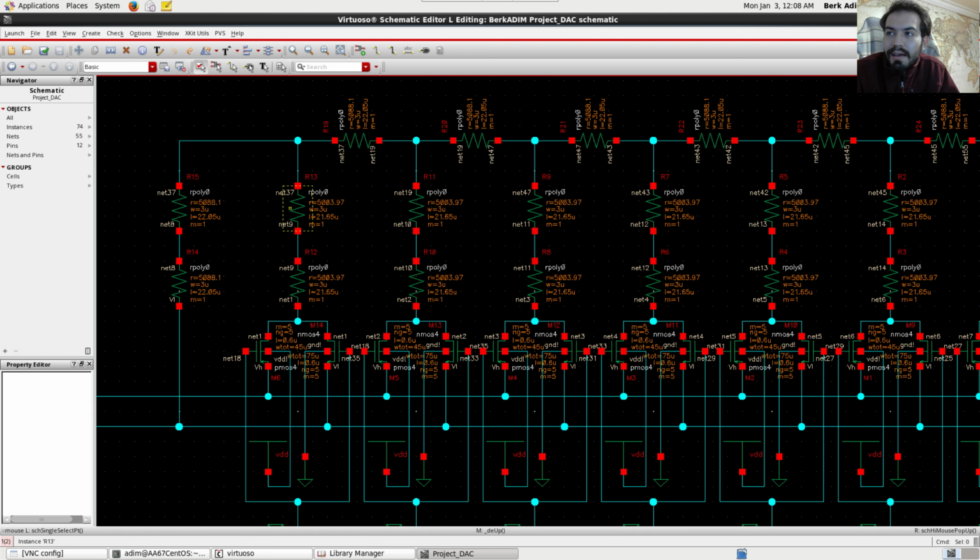For instance, we have a 4-volt range 8-bit DAC here, so we have 256 steps, and at every step we expect our output to move up 15 millivolts. If you don't have good monotonicity, it might just move up 5 millivolts, or it might not move up at all, which is a big problem. If you choose larger resistances, you get more noise, but you get better monotonicity because the relative discrepancies between individual resistances are decreased.